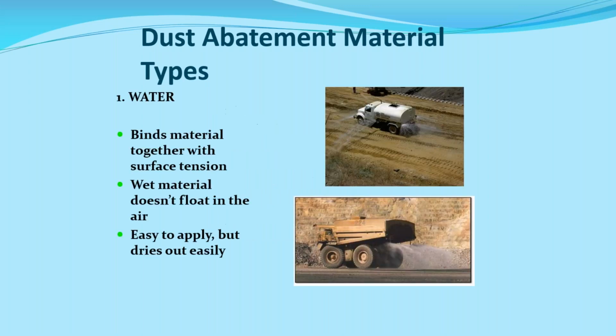So like I said, water. I mean, water has been used for centuries to increase that surface tension of that material, so that binder and that sand and that rock is all stuck together and kind of holds it all set together. And as long as there's moisture there, they'll hold it and keep the binder from floating off and having problems.